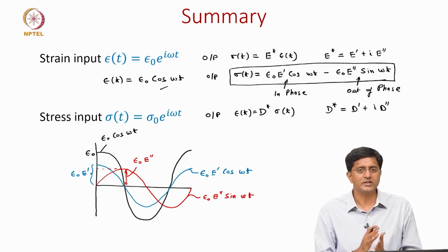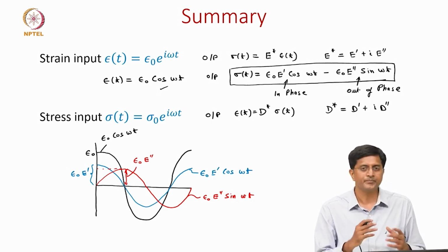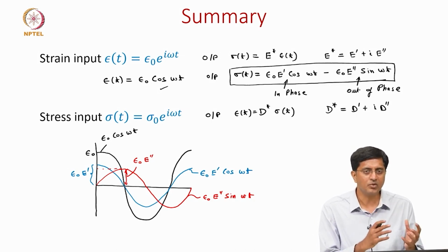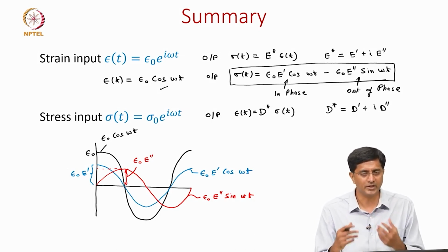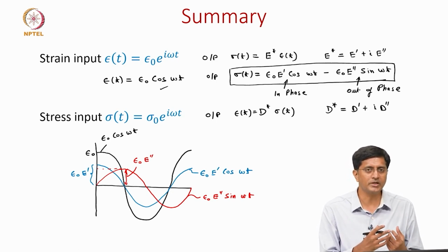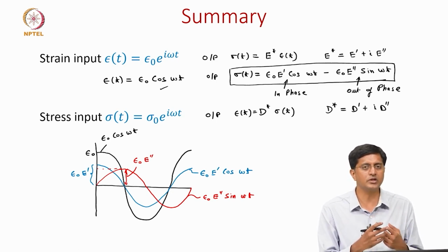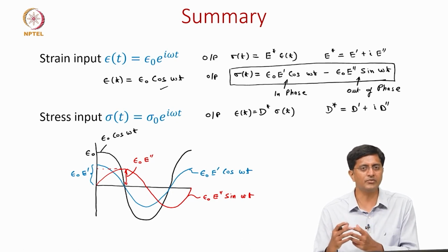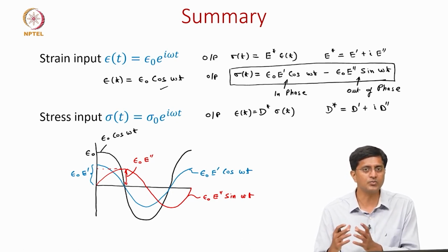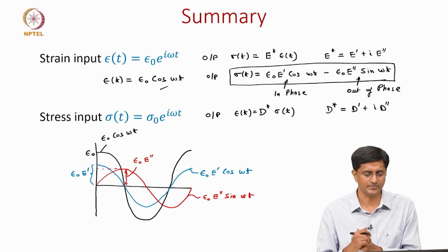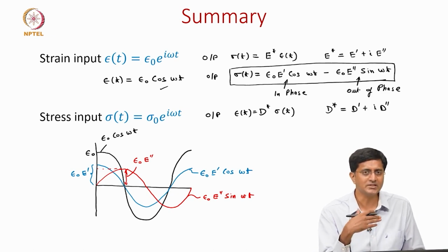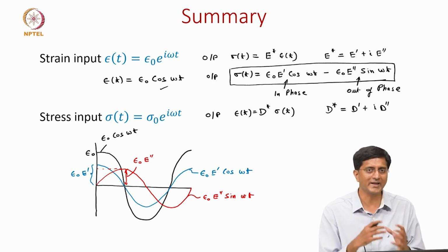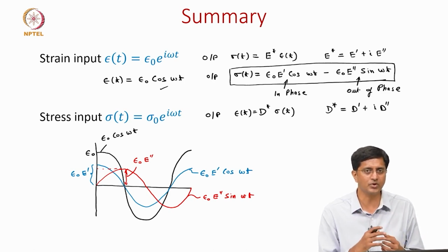So, just a final statement saying that there is an in phase component and an out of phase component in the response. The in phase component is coming from the storage modulus or the storage compliance, and the out of phase is coming from the loss modulus or the loss compliance. So, in the next class we will solve some problems and see how we can bring in the mechanical model to find the response for these dynamic loads.